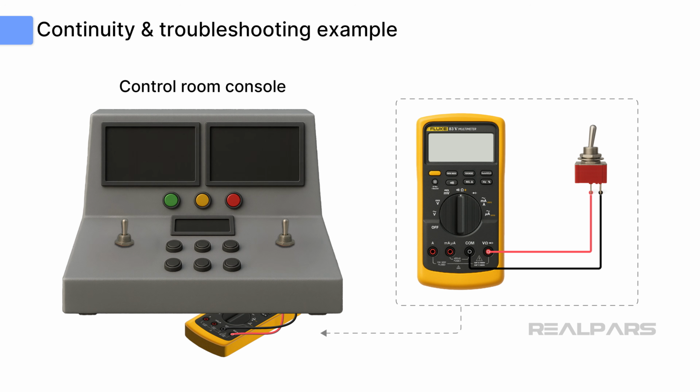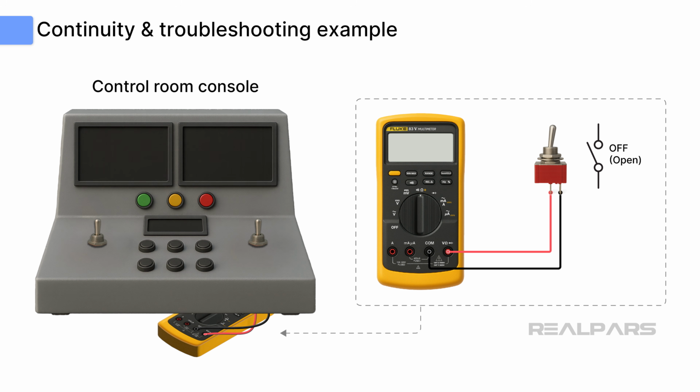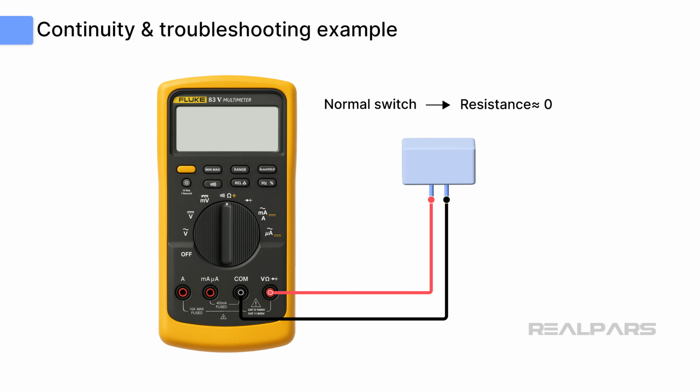Of course, we follow all the rules for using a DMM to measure continuity and resistance. During our test, we found that when the switch is open, the DMM is silent, and when the switch is closed, the DMM beeps. Do these tests indicate that the switch is functioning properly and not the source of the problem? Remember, we can't actually see the DMM screen during the measurements. The normal switch resistance should be close to 0 ohms. So, can we safely assume the closed switch is close to 0 ohms if we hear the beep?